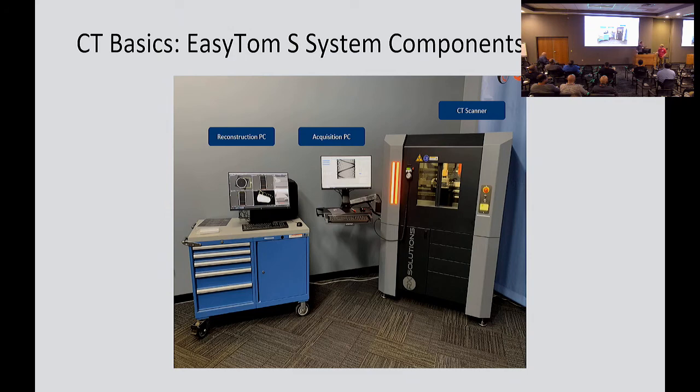Next is Jim. Okay. So one thing we would do there, and we'll kind of get to this a little later, is that we brought in the full first article. So there is all 32 features. And from there, maybe you want to pare it down, and say, okay, what can I measure with the CMM and with the CT? And so, okay, I got 32 in my first article, but there's only 8 features that I can get CT and CMM data, so we just strip it out.